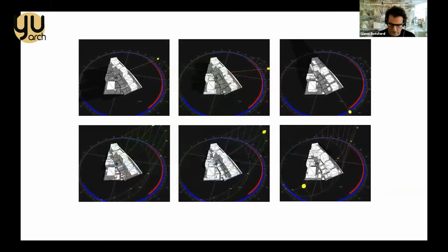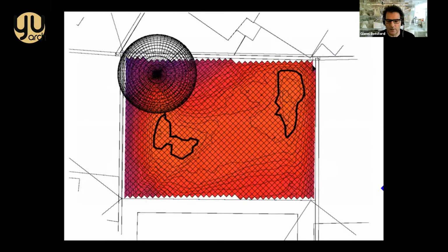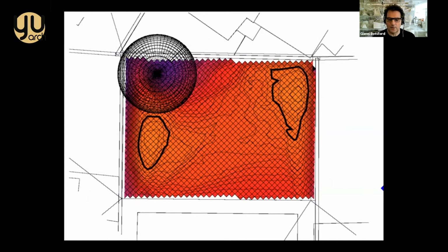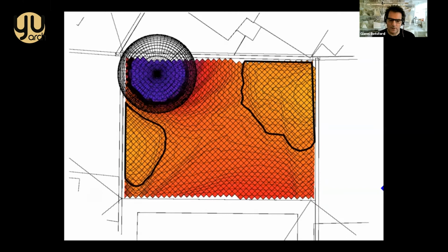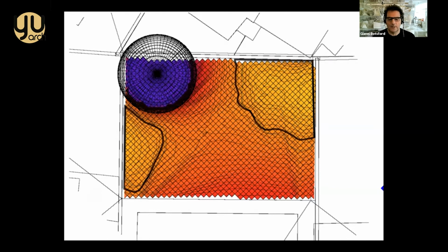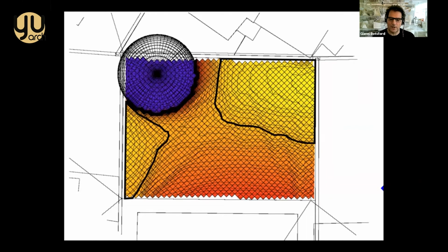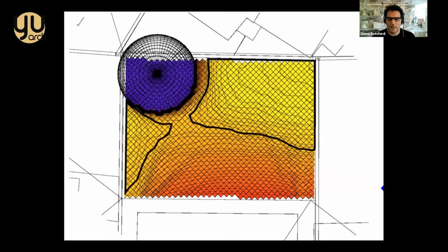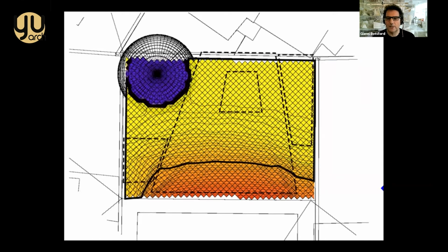So again, we did solar analysis to try and understand it better, and then looked at breaking up that information vertically. So this is slicing every meter and doing the same analysis to try and work out where there are differences on this plot of land between good light and less good light. It is very overshadowed. So there's the very large tree, as I mentioned, but we start to see emerging as you rise up 2 areas where there's a better level of sunlight during the year. These are annual programs. So we are identifying really where could we put gardens that would be sunny. And the idea emerged of an oculus, a big skylight towards the rear and to the middle that you show on the plan here.